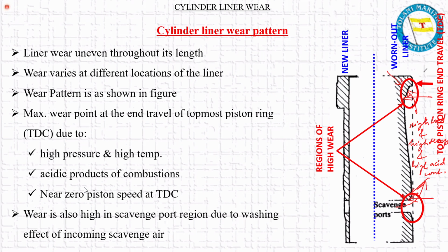Plus the hydrodynamic effect of lubrication is less. The load is very high, so oil film thickness has become very less, and that is why the wear increases. The metal to metal wear increases. So these are some of the reasons which are mentioned over here. Is that clear? Any doubt on the same? No? No, sir. Okay.